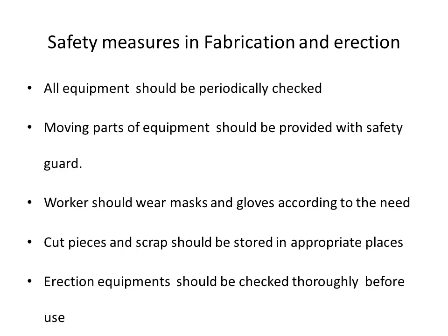Then the cut pieces and also the scrap portions should not be kept here and there in the building. They should be kept in appropriate places, otherwise there is a chance of people getting hurt with these cut pieces and scrap. The power cables of all the equipment should be properly insulated and protected from damage, and also the lifting tools as well as erecting equipment should be checked thoroughly before they are put into use.